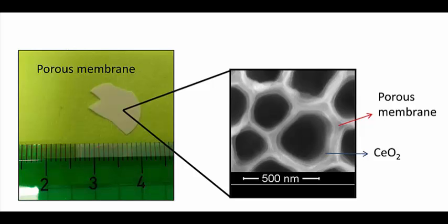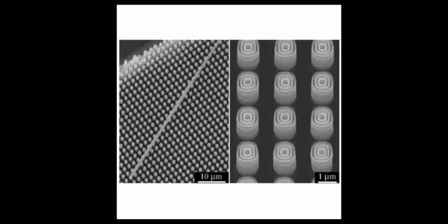The benefit of using ALD to modify the surfaces of nanoporous materials is that, unlike many other methods, the saturation and self-limiting nature of the reactions means that even deeply embedded surfaces and interfaces are coated with a uniform film. Nanoporous surfaces can have their pore size reduced further in the ALD process, because conformal coating will completely coat the insides of the pores. This reduction in pore size may be advantageous in